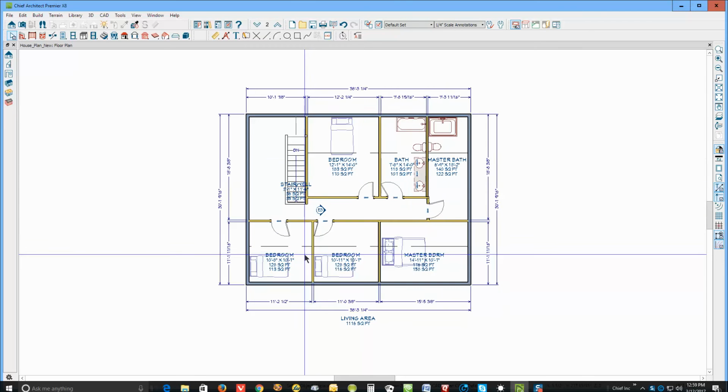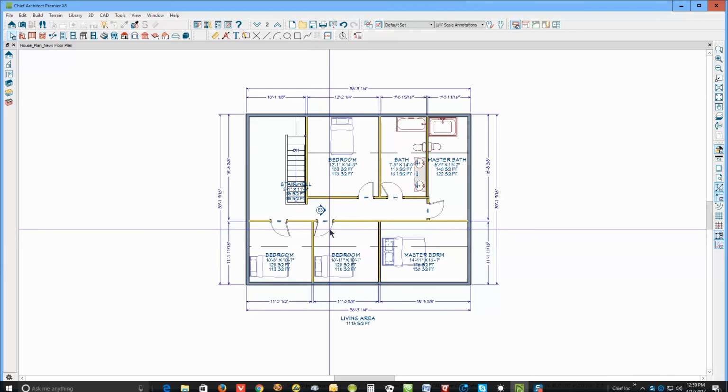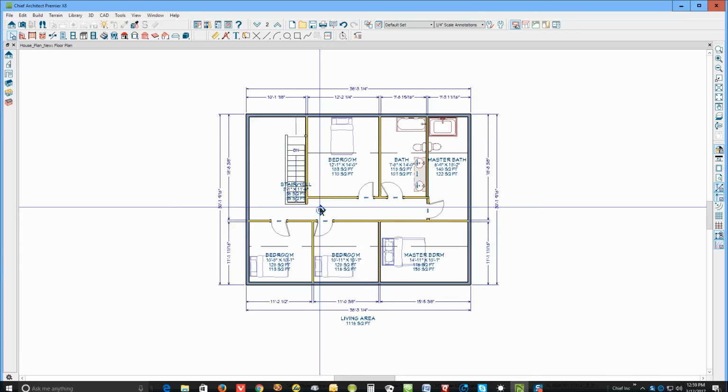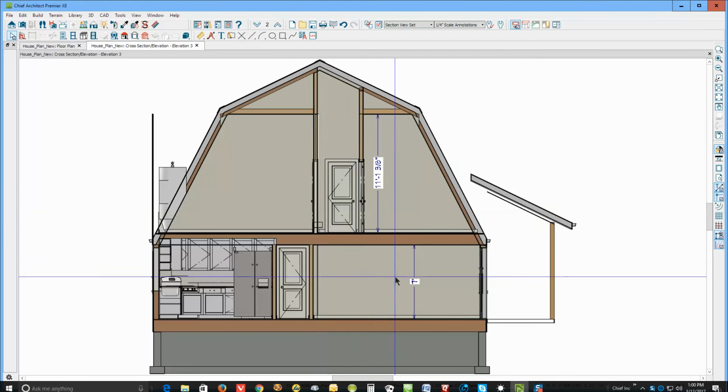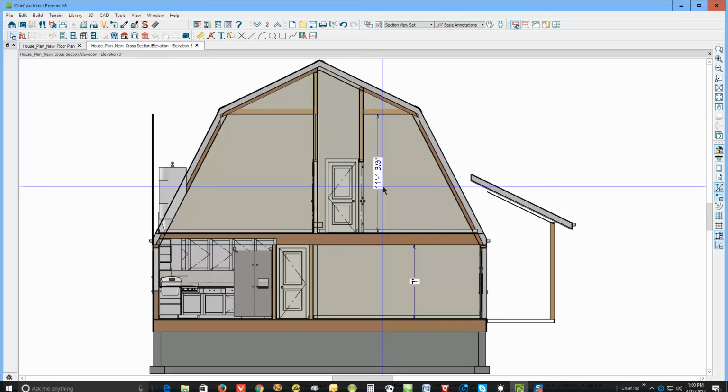And the first thing I do when I look at plans by new people is how they did their default settings. So I've got a saved camera here. I'm gonna open it up and illustrate what I'm talking about. You got the ceiling on the first floor here set at 7 feet. But I'm 6'5", and that just wouldn't work for me. And the second floor is set to a little over 11 feet, which doesn't make any sense to me.